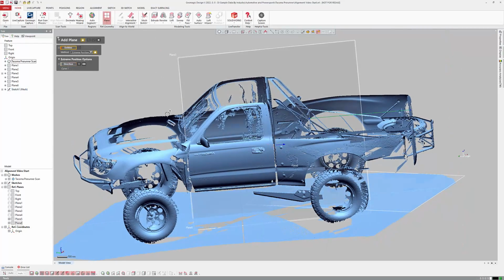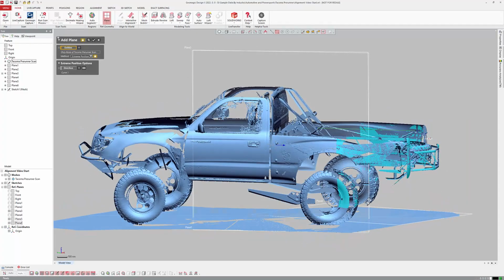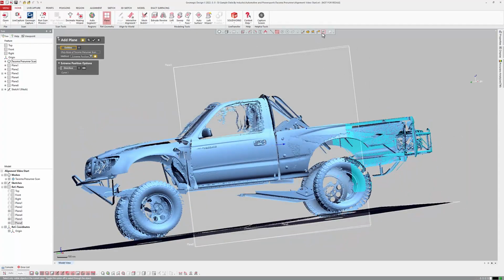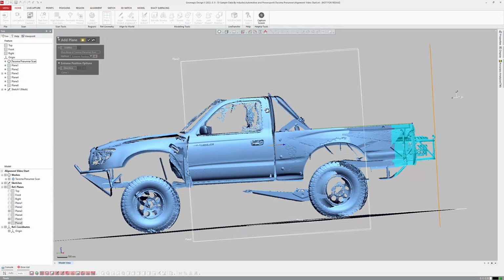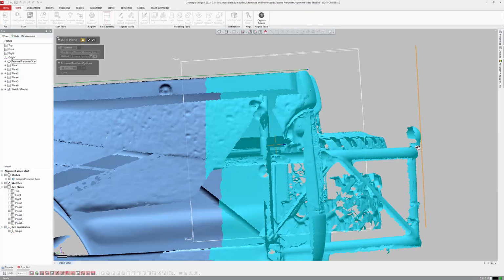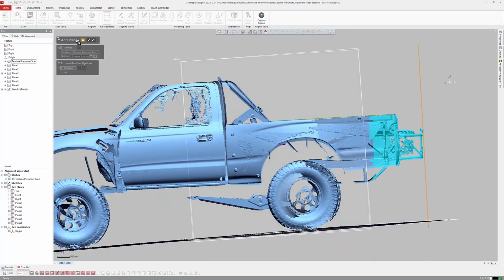And instead of doing the entire mesh, we can, again, just do a selection like we did before. So if I want it to be somewhere on the tube chassis work just outside of that spare tire there, I should probably turn on select through, and again, in that same direction, now I have the very maximum point on that tube in that direction, I have a plane.